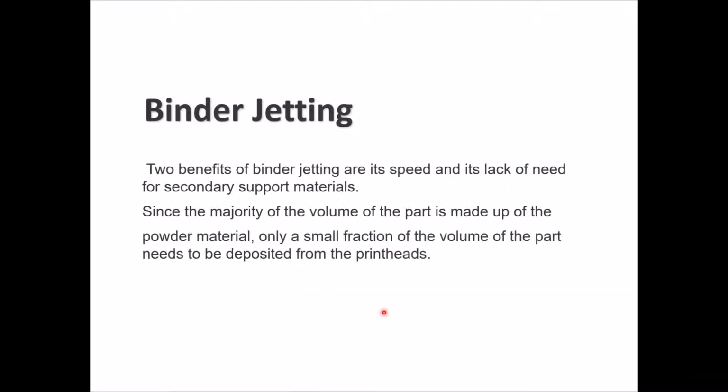The benefits of binder jetting: firstly, it has speed. It's not slow. It's a relatively fast process. Then you don't need any secondary support for the material, basically because your part is sitting inside a powder, so the powder is supporting the part from moving or from falling apart.